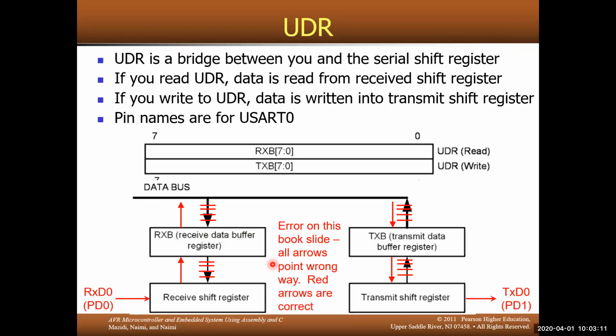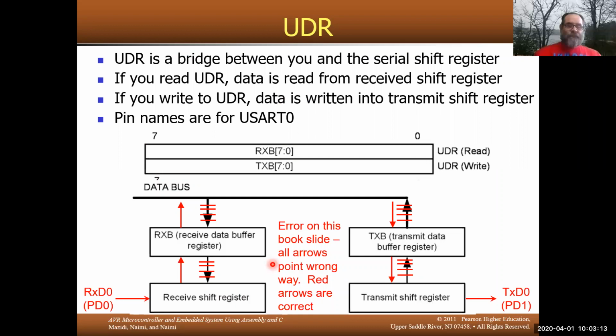Okay, when I finish transmitting a character out, if there is a character in this buffer register, it is automatically loaded into the shift register.